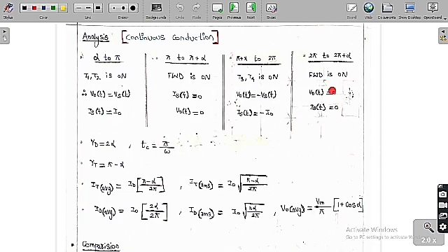Because of this, the output voltage and source current graphs are the same as the semi converter. That is the reason we call the full wave bridge rectifier plus freewheeling diode a semi converter. The conduction angle of the freewheeling diode is 2 alpha, whereas the conduction angle of the thyristor is pi minus alpha.